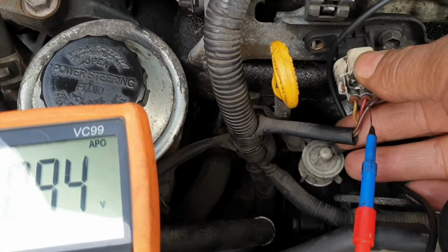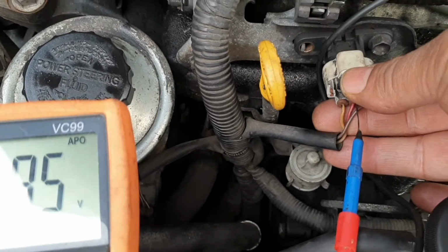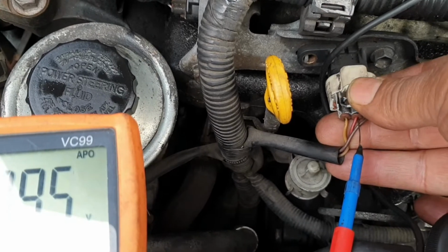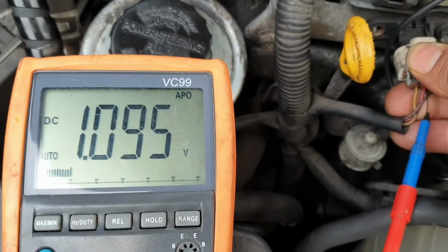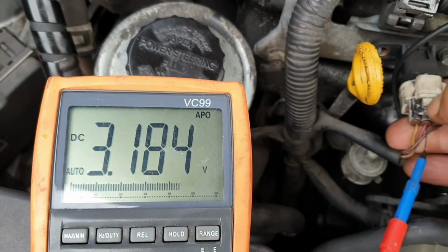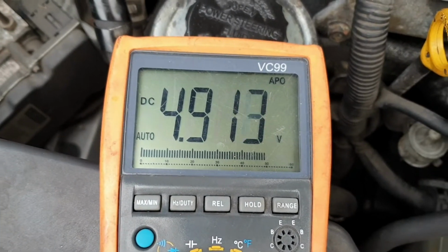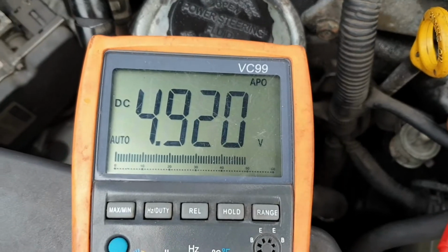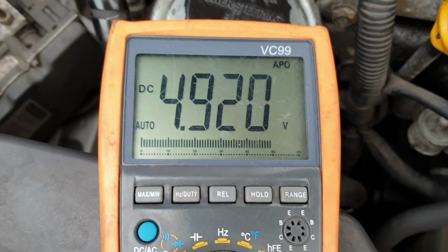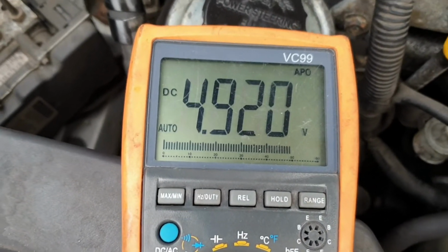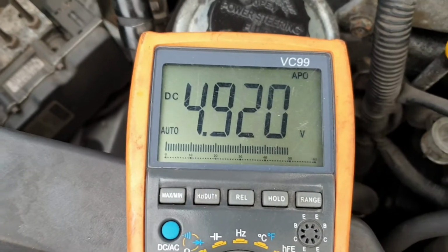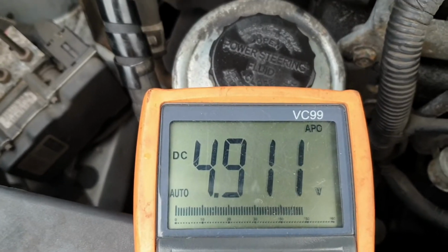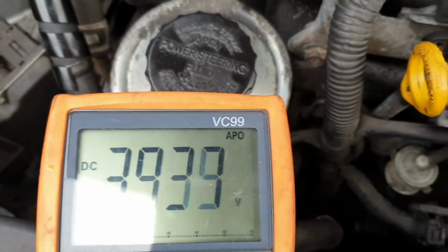Now I'm going to disconnect the sensor connector from the sensor itself, and then you watch. As soon as I disconnected the connector from the sensor, the voltage has gone up to 4.9. So whenever you are confronted with this type of situation,